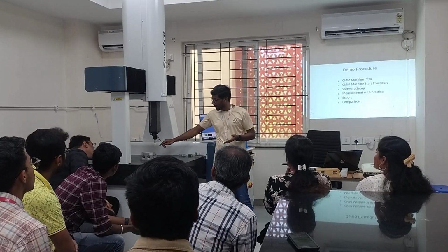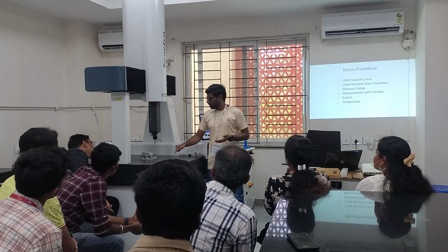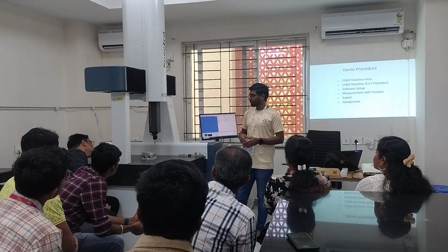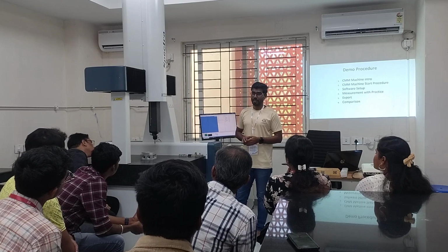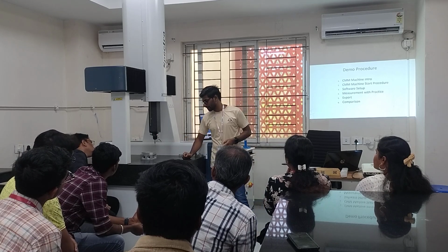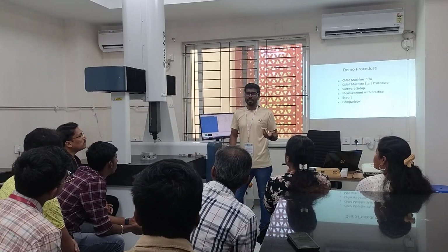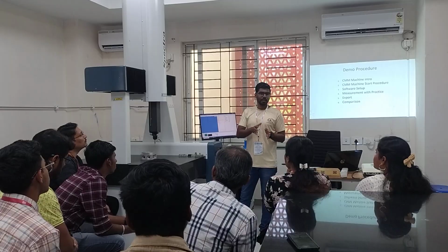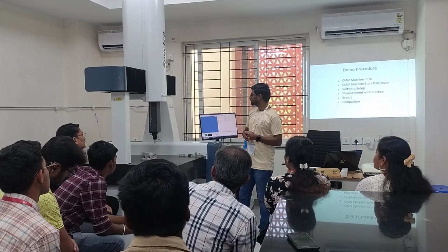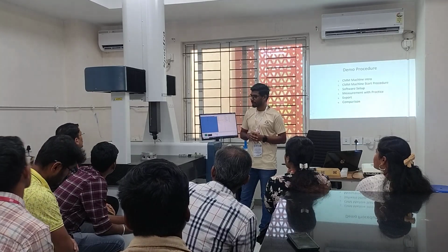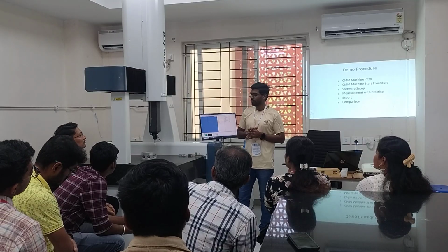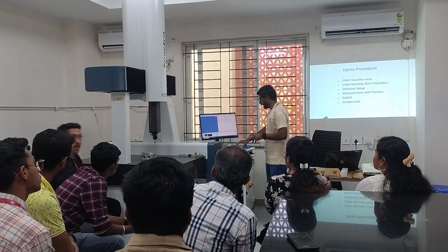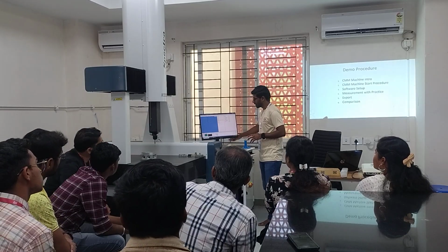It is scratchless because several times this probe is going to touch our part. Even water just dripping on a stone makes a way, so the probe itself could get scratched. That's why we use ruby. Another reason, it is very much temperature resistant. Expansion and contraction of ruby is very little when the temperature increases or decreases. And for this environment, we have to maintain 20 degrees plus or minus for measurement so that we get accurate measurements. So this is about the machine, and I will start explaining a bit about the software.